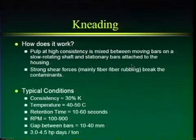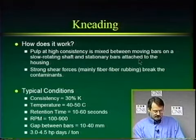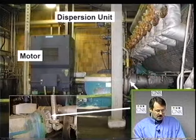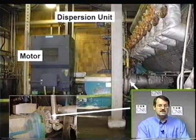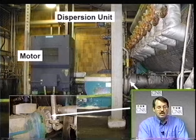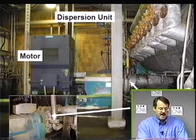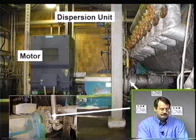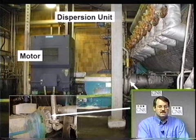Okay, so that's disc dispersion. To review disc dispersion, we use intense mechanical action. We have to heat the pulp up. The pulp's at high consistency, and it passes through these close gap teeth. The unfortunate thing about disc dispersion is that it does cut a lot of fibers, and that cutting action can be a problem if strength is an issue or runnability on your paper machine.